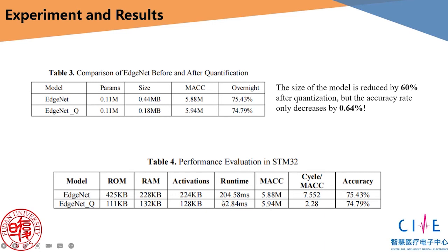Together with the data acquisition and the preprocessing algorithm, the quantized model performs a complete sleep posture acquisition and classification algorithm in less than 16.5 milliseconds. This proves that the proposed system can be used as an edge device to achieve long-term sleep posture monitoring in IoMT.